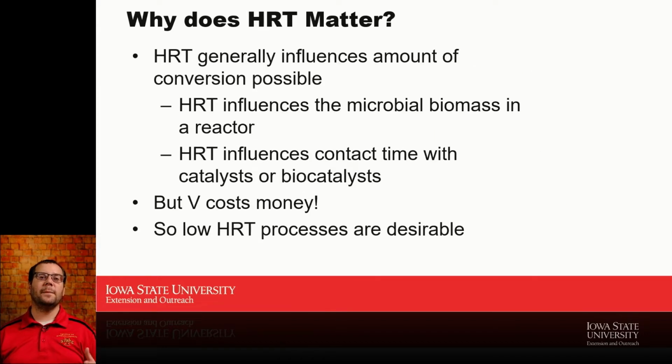So hydraulic retention time matters because it really is how long it's stored in the tank. And how long we store stuff can influence how well we develop that microbial biomass, how active they are, how many of them are there. It can also influence their ability to interact with food, right? So if I have too many microbes and not enough food, I've sort of starved my system and I could probably add hydraulic loading. If I have too few microbes and too much food, well, it takes a long time for them to eat everything, and I could probably adjust it to save myself some money in that process.